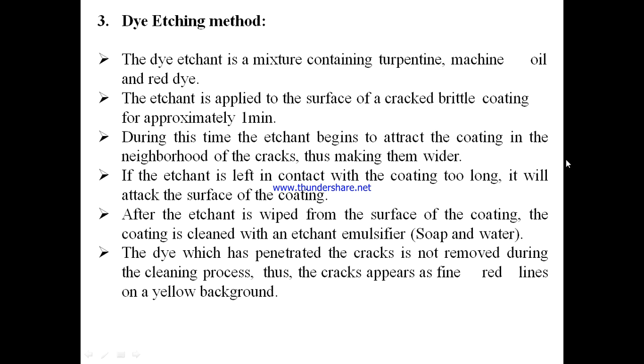The dye which has penetrated the cracks is not removed during the cleaning process, thus the cracks appear as fine red lines on a yellow background. The fine red line is due to the red dye.